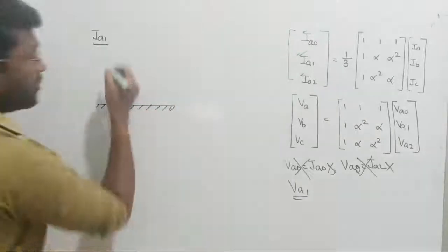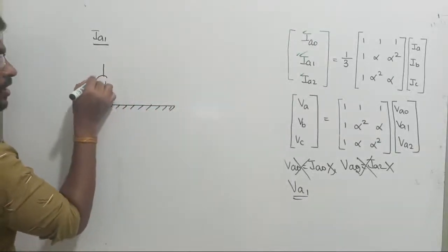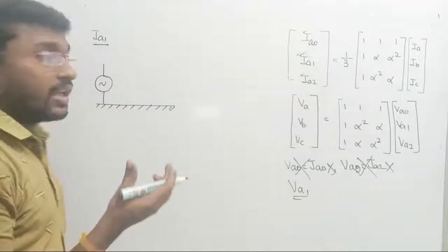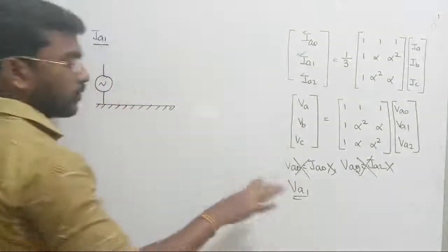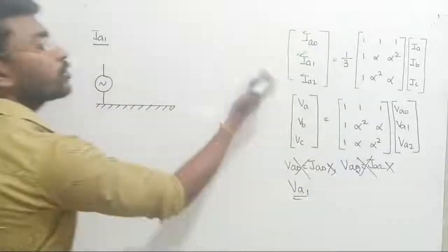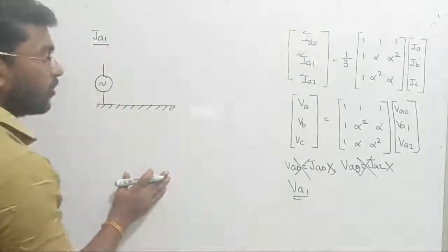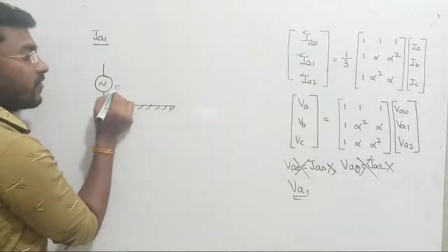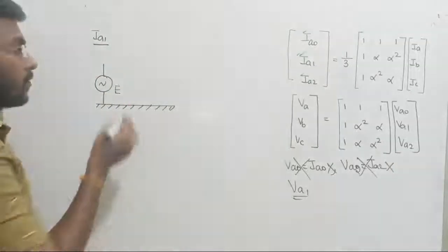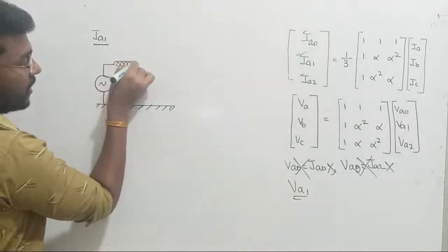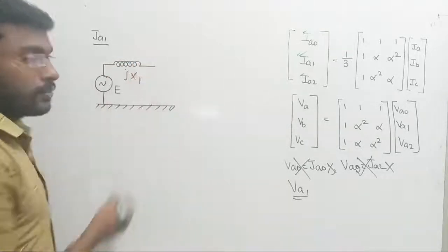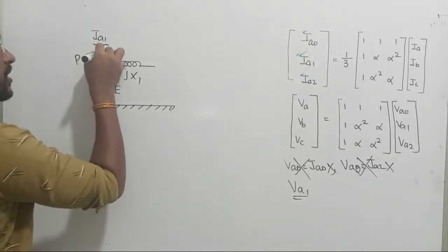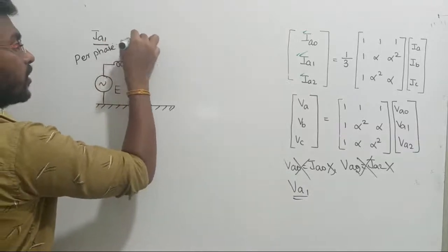whenever we are looking for positive sequence current, first we have the positive sequence of the normal sequence, correct? Guys, just take your previous one, right? Just see the equivalent circuit. From the alternator we are observing, during the positive sequence, the maximum current delivered by the alternator to the transmission line. For positive sequence we draw the equivalent circuit from the alternator. We have to consider the effect of the induced voltage of the alternator, along with the positive sequence reactance. That can be simply written as JX1, right? That is the per phase equivalent circuit. Don't be bothered, that is the per phase equivalent circuit.